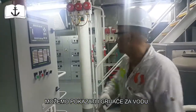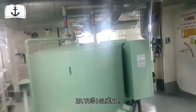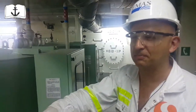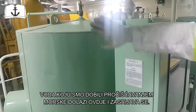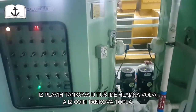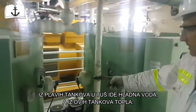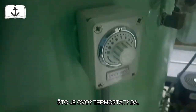We can maybe show also the heaters there with the water. Sometimes you need hot water because you're not taking a shower with cold water. Shower water is the most important stuff on board. So these are the heaters. Americans call it a calorifier, in the UK they call it a heater, we just call it a hot water tank. Basically it's really simple. The water we push to the accommodation goes there, and in these tanks you have the electrical heating coils heating up the water, and then you have the circulation pump. It's separated: cold water goes to the shower directly from the blue tanks, and from the green tanks hot water goes the other way. So we can heat a lot of water. This is the thermostat, you set it up here.